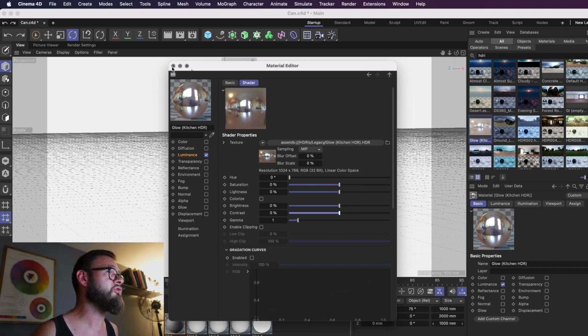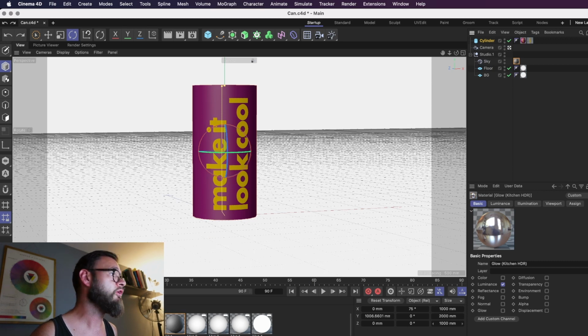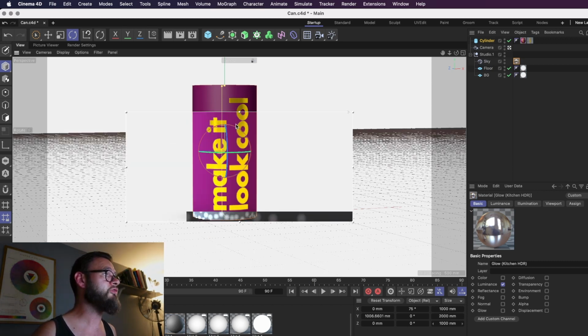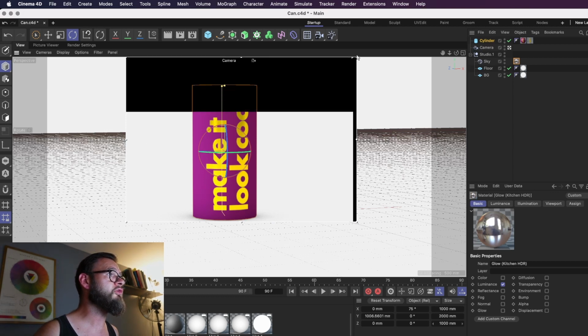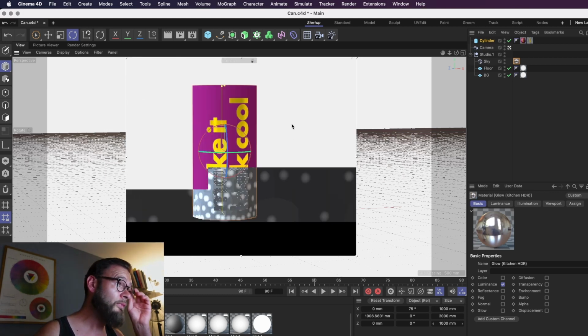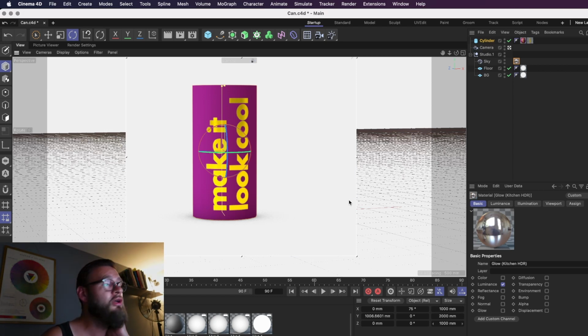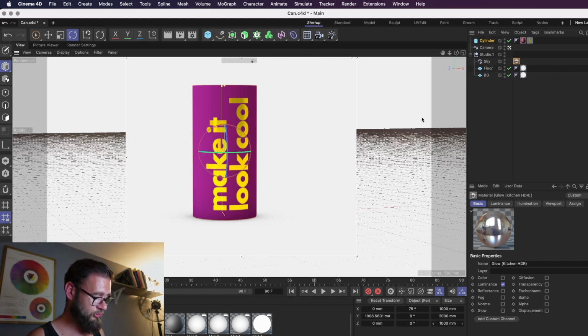I'm gonna leave it the default now because I just want to apply it to that sphere. So drag that over to the sphere, and let's see. So we have some reflections going on there. Now what I normally do, because the floor will knock your reflections out, that's always a bit dodgy, is you can use the compositing tag, like I showed you in the last tutorial, or maybe it was one before, I can't remember. You can use the compositing tag to knock the floor out.